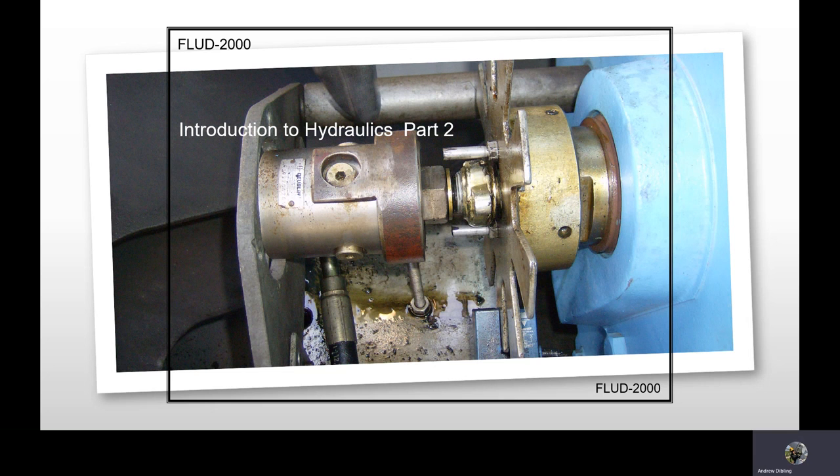First slide we're looking at here is a small hydraulic motor. This motor is driving this shaft, which will help position a wind turbine rotor. So this is a positional motor that can go both directions and has very precise control, which is something that hydraulics can offer.